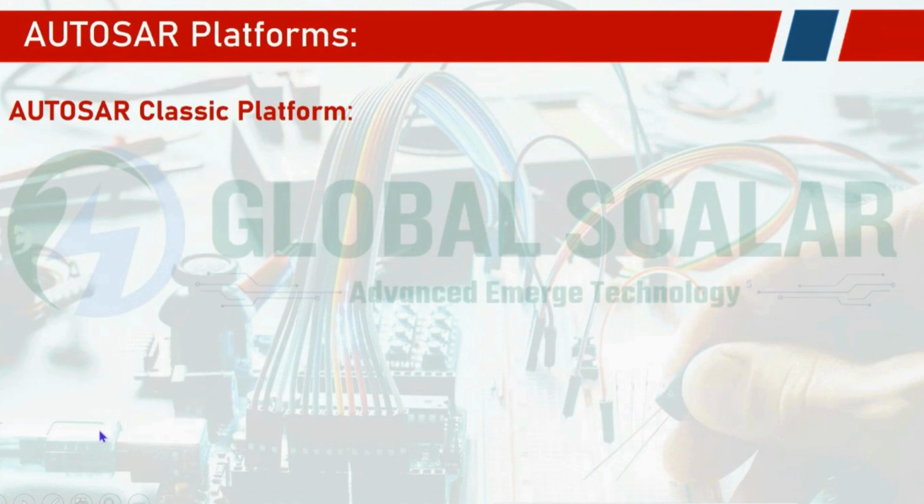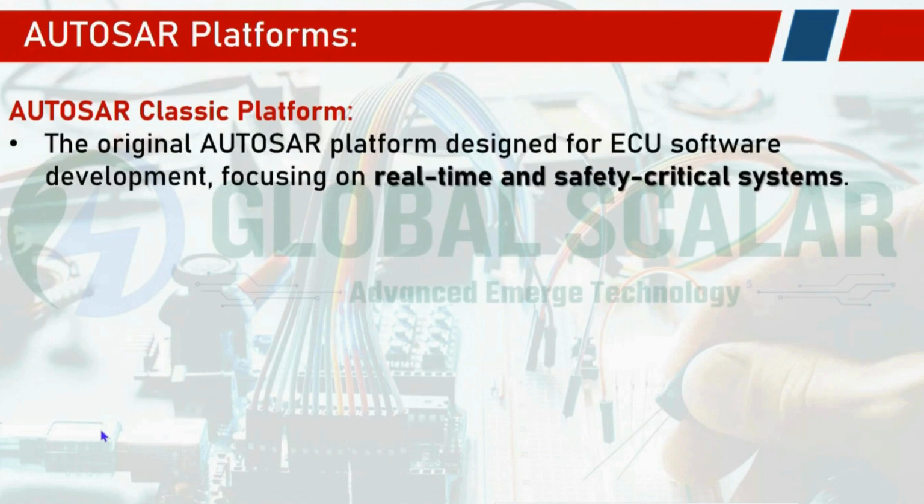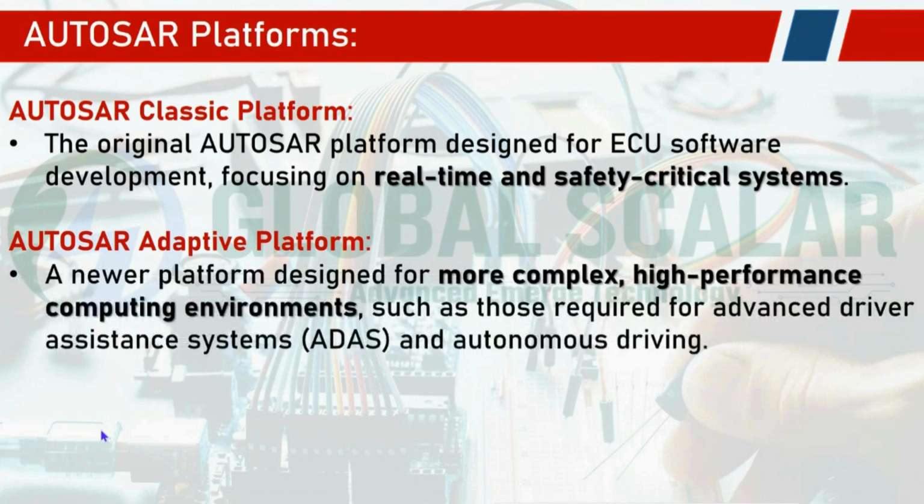So Autosar is categorized into two platforms. The first is the Autosar Classic platform. It is the original Autosar platform, specifically designed for real-time and safety-critical systems. The other platform is the Autosar Adaptive platform. It is a newer platform specifically designed for more complex and high-performance computing environments, such as ADAS, Advanced Driver Assist System, and autonomous driving vehicles.